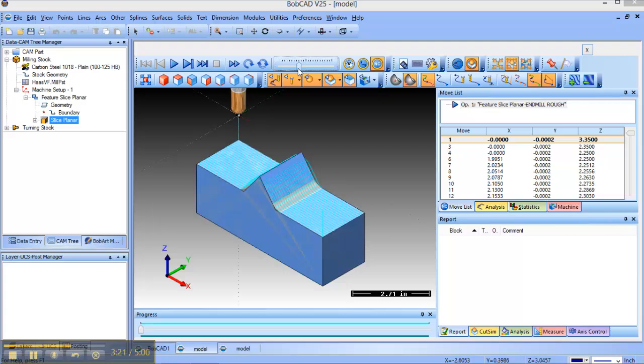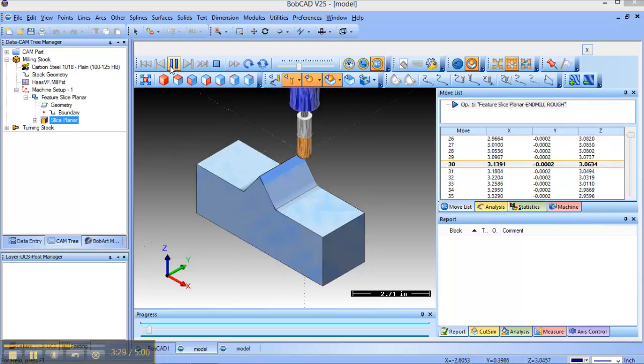We're going to slow this down just a little bit. I'm going to get rid of the tool path here. I'm going to click on that and click that, and then we'll just hit run. I'm going to just let it watch a little bit. Now you notice how I have this angled piece here in our STL and then how it's going away. It's a great part of using an STL, that it's actually showing everything that's going to be taken away on there.